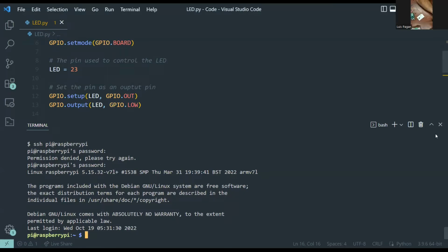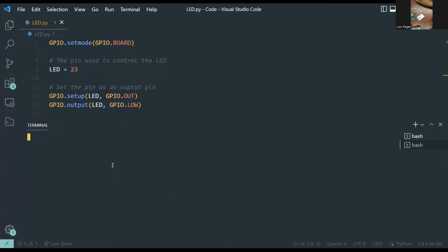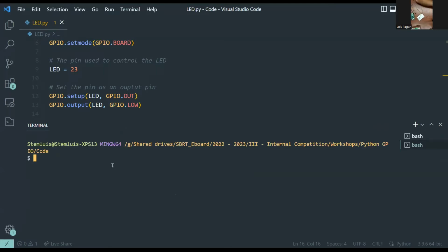All right. I guess I'm going to show you guys, if you didn't know already, how to do that. You have to make sure both the Raspberry Pi and your computer are on the same network. Then either through PuTTY or whatnot, you do something along the lines of SSH. This is in Bash, common in Linux and Mac OS. It's different in Windows. Actually, no, I think Windows is also pretty similar. But I'm going to do SSH. I'm going to put the username, which in my case is Pi, and the host name, Raspberry Pi. Hit enter. Then it's going to ask me for a password.